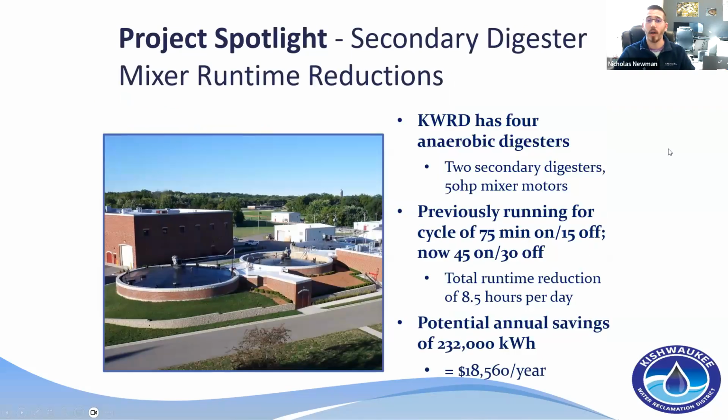Next, we have our second project type, which is run times. This was a really big ticket item for us. We have 4 anaerobic digesters. 2 of those are secondary digesters that each have a 50 horsepower mixer motor. You can see our digesters in this nice picture here. Previously, before we did anything, we were running them in a cycle of 75 minutes of active mixing and 15 minutes of idle or off time.